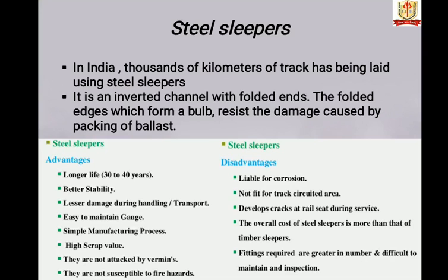Steel sleeper. In India, thousands of kilometers of track have been laid using steel sleeper. It is an inverted channel with folded ends. The folded edges, which form a bulb, resist the damage caused by the packing of ballast.